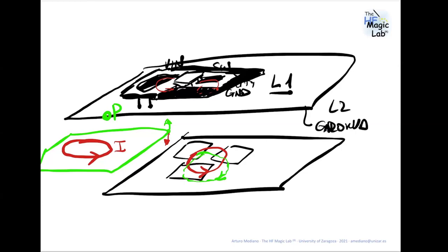The idea is to be able to have the high currents circulating in the dirty ground in the top layer. Right? Anyway, if you are not able to understand this concept, don't do that, and put the ground plane below the components of the IC and all the switching nodes, as close as possible.